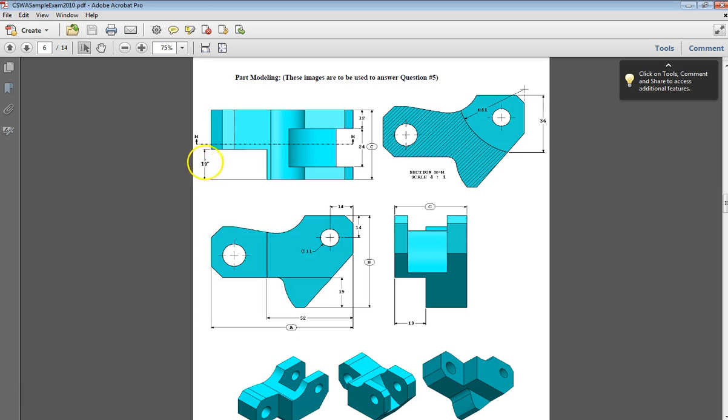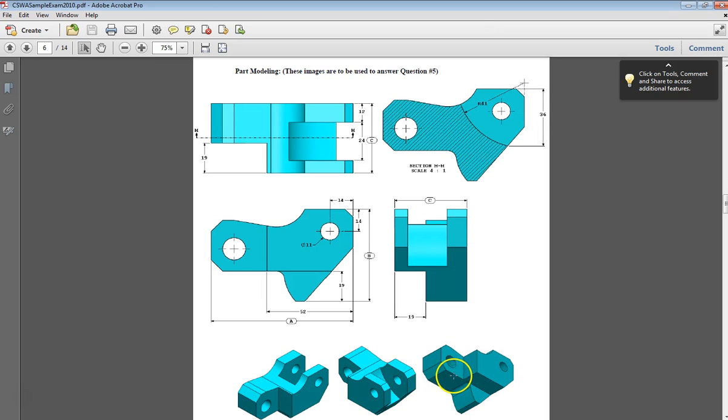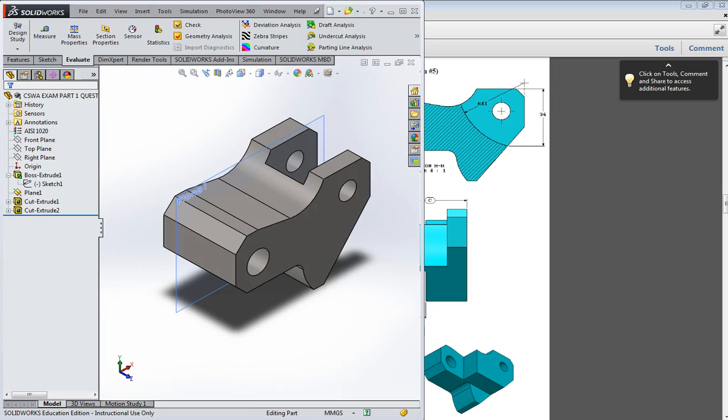And definitely this 19 is important. It's showing you from the top view that that's where this line goes back. And then you can see this bold line right here, the object line. That's 52 over from the right. So 52 and 19 are the key, but also look, you know, this section's cut here, but also down here, this area is also cut. So when we look at the SolidWorks part right here, you know, this area in here is going to have to also be shaved away. So there's two things that has to happen.